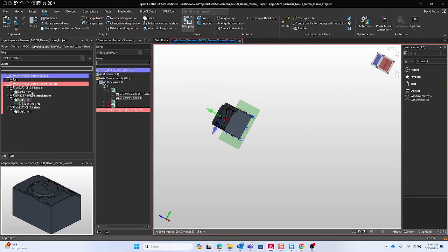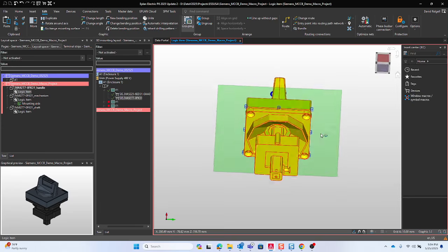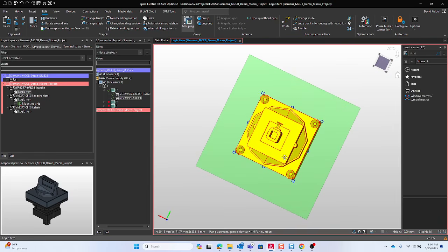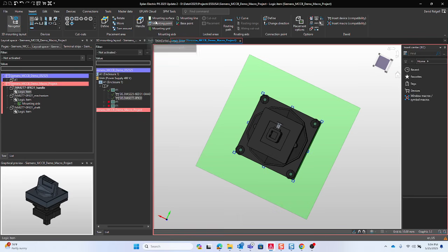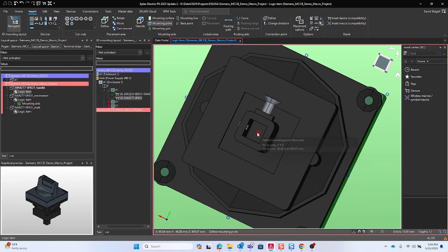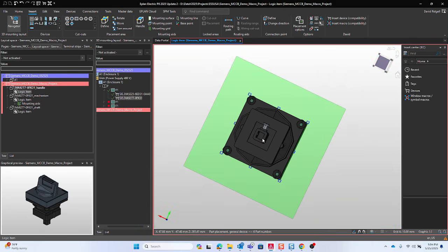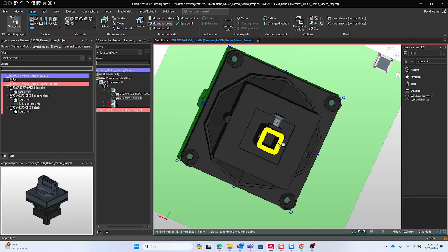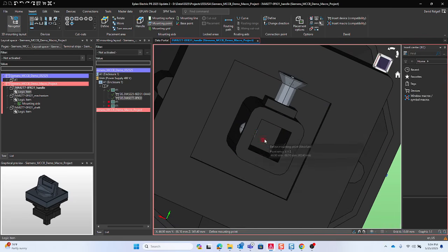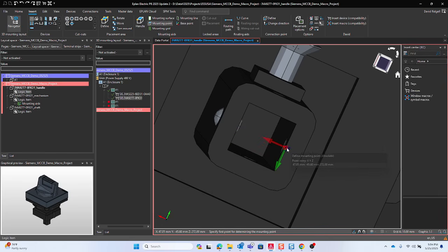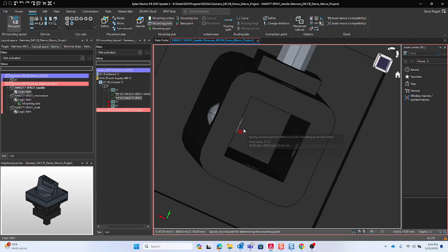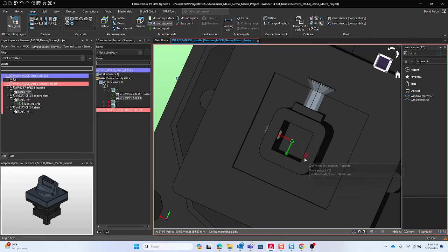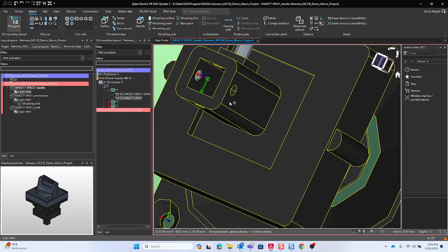And we need a similar thing on the handle, so we'll go over to our handle here. We'll do the same thing. Insert, mounting point, place it on the center right there. Looks like I may have lost it, so I'm going to Control Z, undo that. Mounting point, I'll actually do it right here, and I'll just select the midpoint of that one while I'm holding Control, select both middle points, and it'll center it up for me from both sides. Control, and now it's there. And then I'll end up just moving it in a little bit.